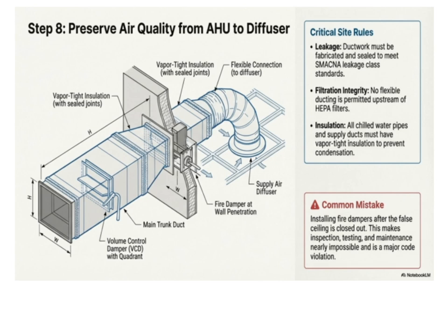All insulation used in the system must be vapor-tight. This prevents moisture from penetrating the insulation, which can lead to condensation, mold growth, and even infection risk, something we certainly want to avoid. Fire dampers play a vital role in safety.